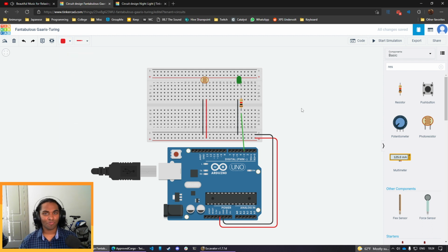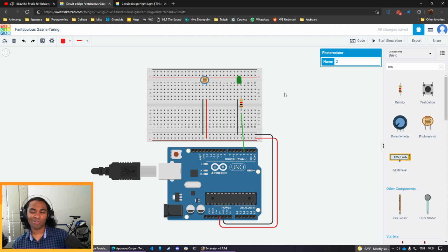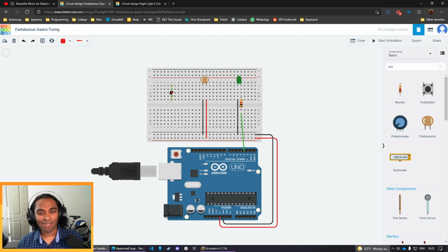Okay, so what's wrong here? Well, for starters, we don't have a resistor in place. I know it's a photoresistor, but there's still a possibility, well, sorry, I'm explaining that wrong. Let's start over. The real thing that's wrong here, more than anything else, is that we have no way to measure how much current is passing through our photoresistor. That's what we wanted to measure, right?